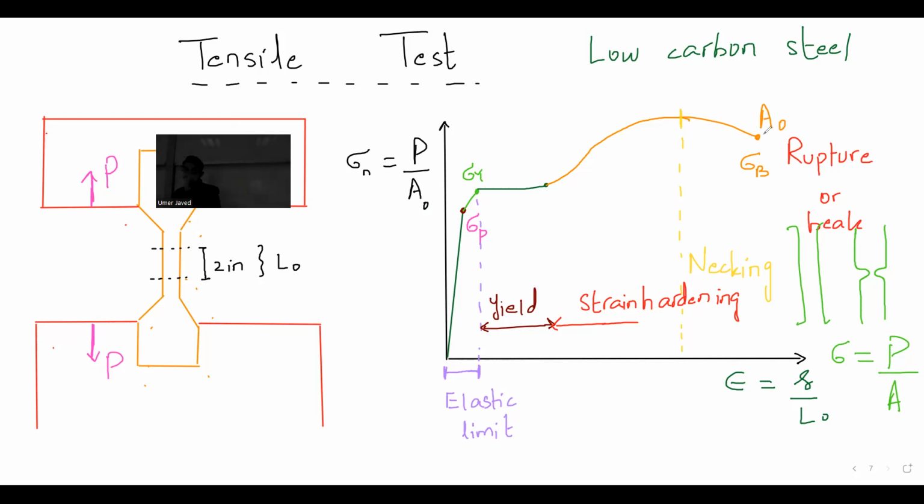It is increasing, but the area is increasing, so it is inversely proportional. Yeah, but my point is the A naught that I'm taking is the original area. I'm not talking about the net area. So for me, this A naught remains constant. That's why you can see a drop here in the rupture, because the denominator for me is not changing, because I took the denominator like that.